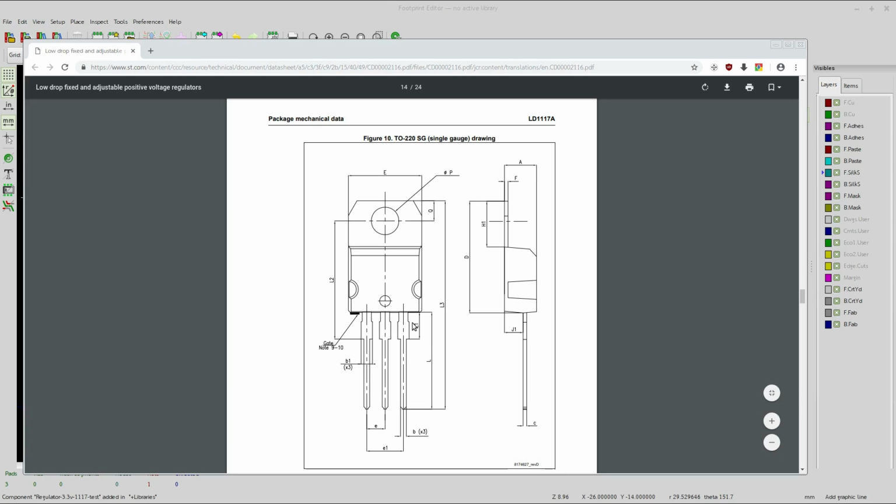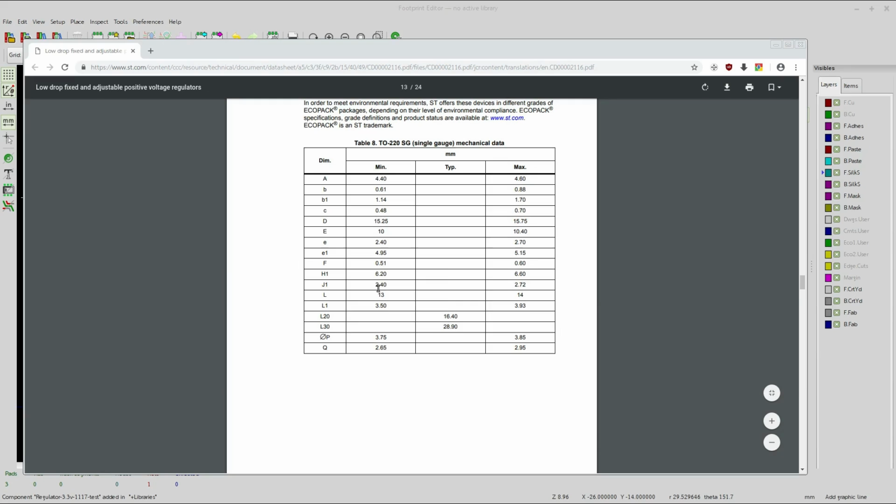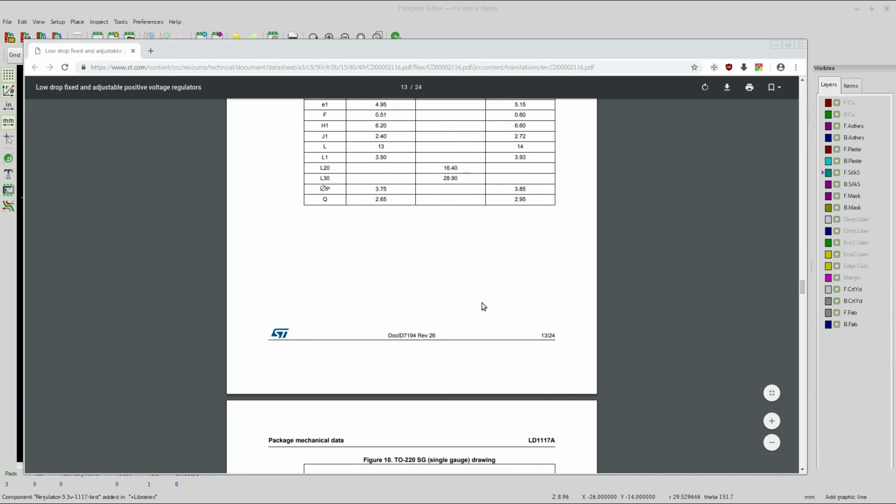We've got L1, and then I want to draw your attention to J1 over here. So L1 and J1. J1 is the distance from the bottom of this pin, inside edge here, I guess, face, to the bottom face of the TO220 package. Okay, we come up here. J1 at most, let's say it's like 2.5 millimeters, 2.6. Okay. L1 is 3.8-ish or something like that. So off the top of my head, it gives us like a millimeter or something to play with.